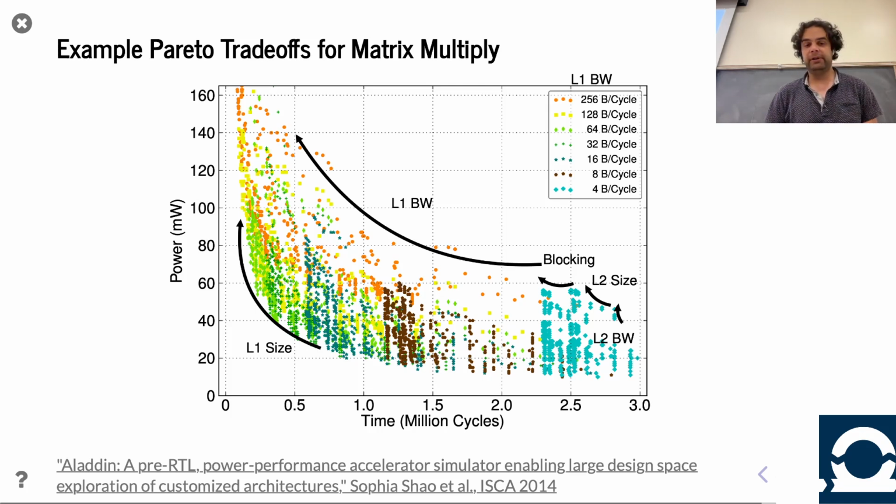And so this is a person that used a Windows model system. So they made a lightweight model to do matrix multiplication, and then they generated a zillion variants and evaluated them. And so you can see here's that same shape we were talking about, right? Where in this case, they have performance as time and power as the two metrics of both the P's of PPA. Lower is better for both.